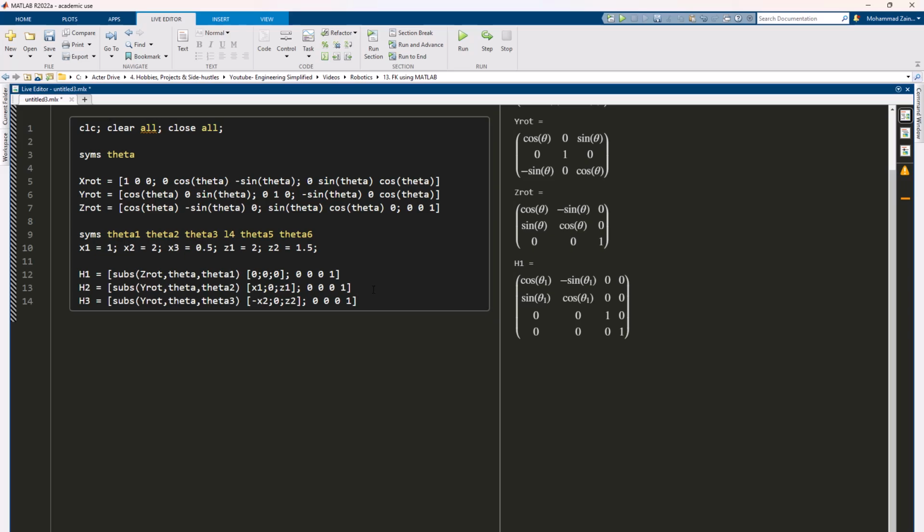and my h4 was, it consisted of a displacement by a4, 0, 0. Now remember that a4 is one of my prismatic joints. So the value of a4 can change. So a4 0, 0, and there were two rotations involved. The first was about the y-axis by theta 5, and this was followed by a rotation about the x-axis by theta 6.